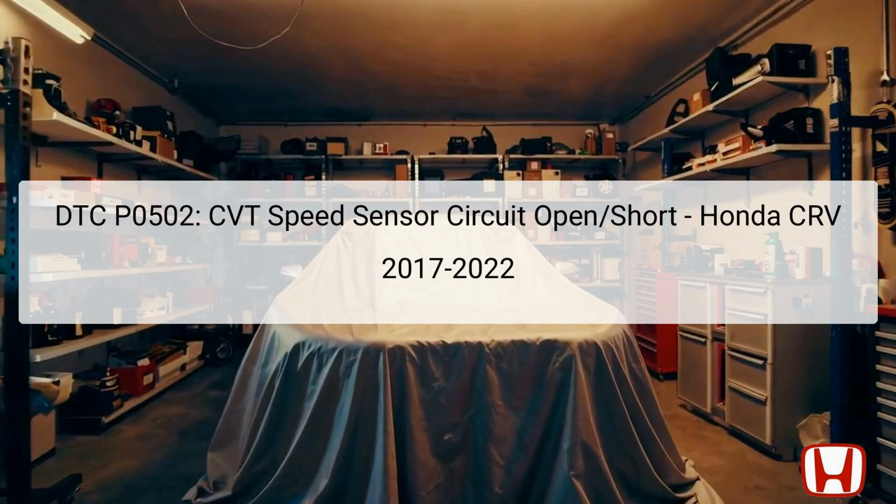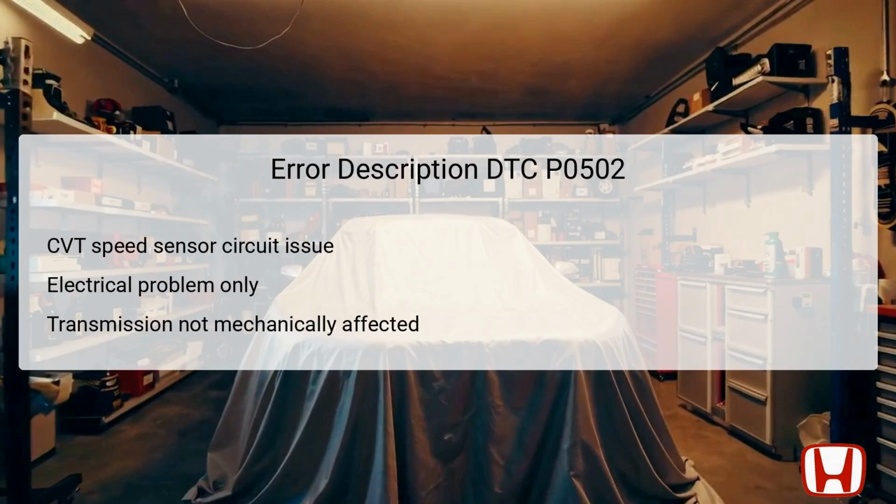The sensor is typically located near the transmission assembly. Troubleshooting this DTC is important for maintaining proper vehicle function, as a malfunctioning speed sensor can lead to transmission issues or degraded performance, ultimately affecting drivability. The DTC P0502 indicates that there is an issue in the CVT speed sensor's electrical circuit. It is essential to note that this error cannot be caused by mechanical problems within the transmission itself, which rules out any physical damage or malfunctions of the transmission components.